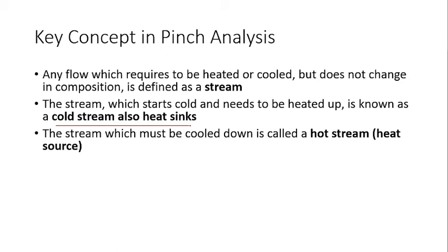Now mind well, when I talk of hot stream and cold stream, because of our natural mindset, we always tend to think that hot stream will always have a temperature higher than cold stream. That's not necessary. How are we going to define cold stream? A cold stream is a stream which starts cold and needs to be heated. So say for example, I have a stream which is going from 30 to 60. So this is a cold stream. And I have a stream which is 100 and going to 70. This is a hot stream.